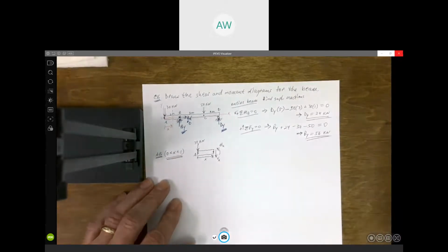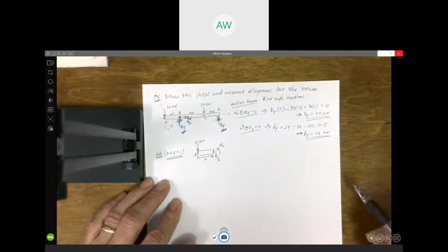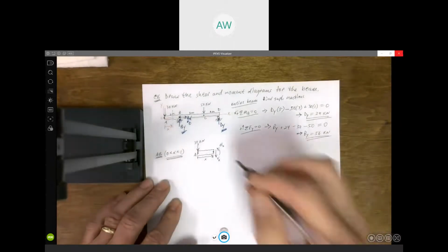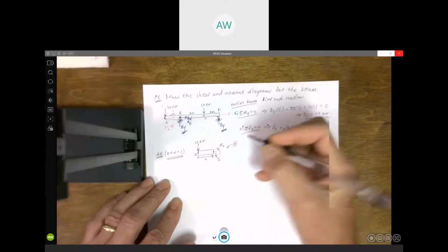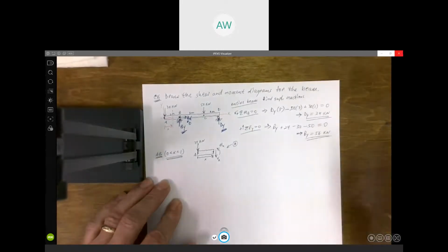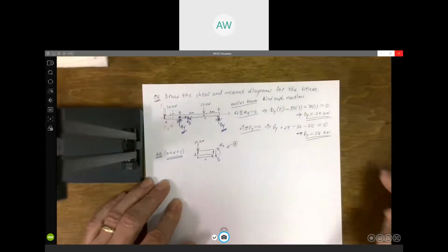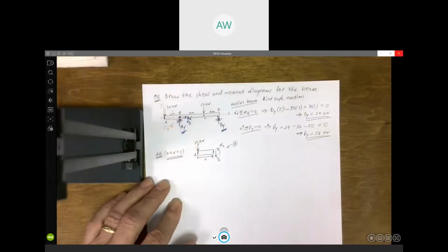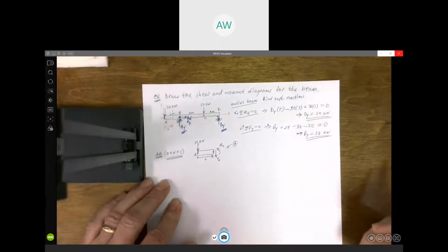And we apply our equilibrium equations, solve for those two unknowns. One other thing before I do that, just a note here. I highly encourage, if you want your equations to produce the correct graphs, you need to assume that V and M are in the positive direction.